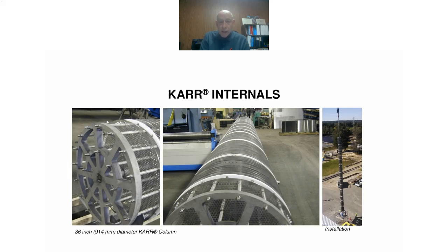And then you got what we call spider plates. These are heavy-duty plates that you see, in this case, one on each end of the column, one in the middle, so that when you tie it together with these tie rods, that's what makes this a very rigid structure.